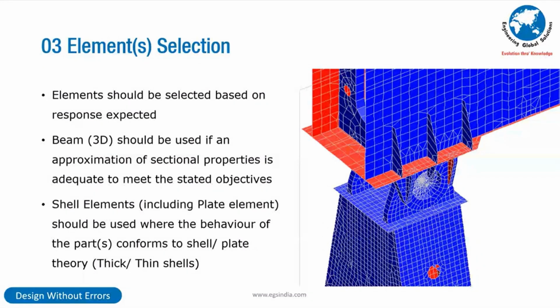Right? So in other words, just like a patient goes for a scan and gets to know what the problems are, whether there's a fracture or not. The doctor recommends a scan and he goes and does the scan to see if there's a hairline crack or not. That is only a confirmatory tool. The orthopedician is actually suspecting a fracture and is only confirming it. Similarly, you have to suspect a failure mode, estimate it, look at its SOD, and then come back and do the finite element analysis and look for it. Otherwise, we'll be looking for innumerable failure modes like a needle in a haystack.